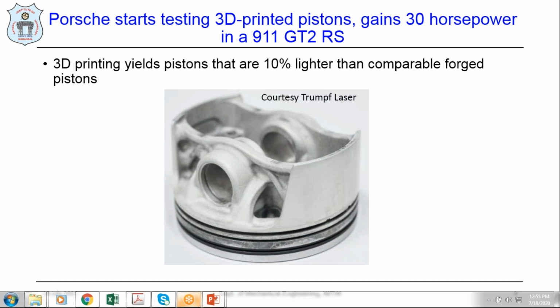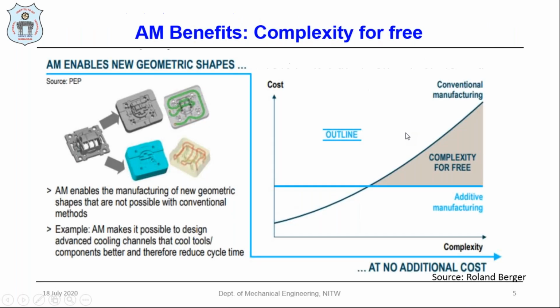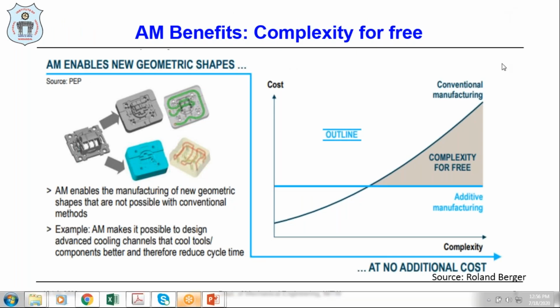For example, take the fuel nozzle that GE has fabricated. With traditional manufacturing, in casting or machining, about 20 pieces of assemblies are required. It may take so much time to fabricate, and I need to go for the assembly process. In some cases it is impossible to machine as a single component, or very uneconomical to cast as a single part. In those cases, we have to go for additive manufacturing to fabricate components with very wide applications, in medical, automobile or aerospace. This additive manufacturing gives us freedom, and its benefits come when we have complexity in the components.